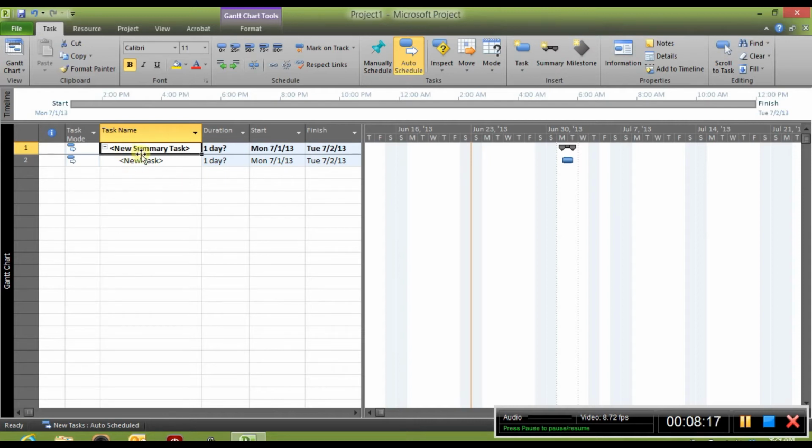This is going to keep track of your entire scheduled durations and finish date. So once you've inserted that summary task, you want to left click on the box and you want to name it. So let's say this is a slab on grade project. So let's just name this construction timeline. You could name it construction duration or construction timeline. Once you've done that, hit enter.